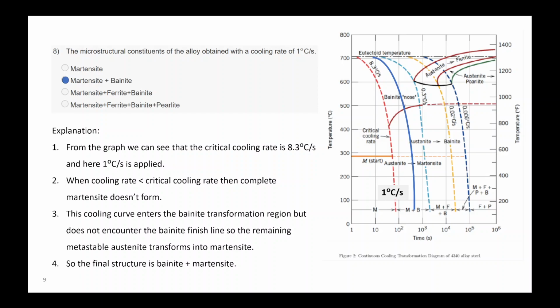Yes, ma'am. On the right hand side, the plus 2 defines whether you can change two things or one thing. So 2 will be when you can change both pressure and temperature. If you can only change temperature, then it will be 1. In case of mainly these diagrams that we use, composition temperature diagrams, for binary diagrams, then you use 1, because you are considering pressure to be constant.